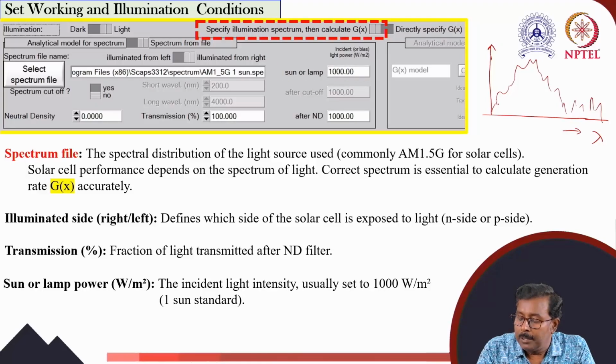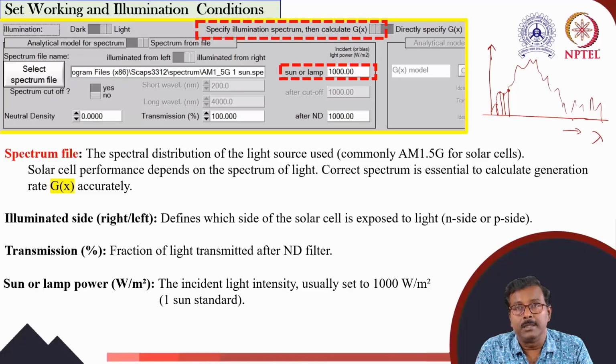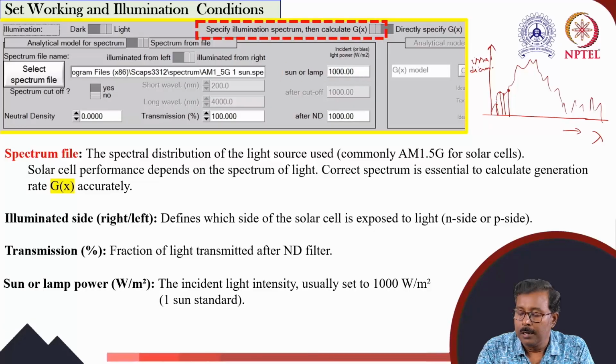At every wavelength from this spectrum file, whatever you are mentioning, you can calculate the irradiance value, all these points, and to calculate the current corresponding to a particular lambda, you have to select values at different lambdas, that is different wavelengths. That is irradiance, suppose irradiance. Total J lambda you have to first calculate at a particular lambda, then you have to integrate over lambda minimum to lambda maximum range, d lambda, to get the total current.